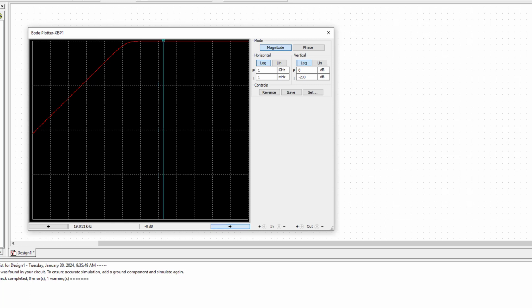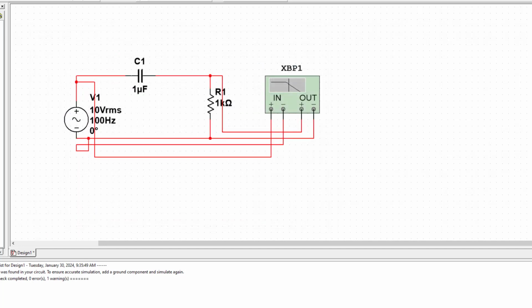the frequency increases, there is a 0 dB. 0 dB in the sense the complete input is just getting applied at the output. So the input is equal to output, and the effect of capacitive reactance is negligible. As the frequency reduces, the effect of capacitance comes into the picture, and the signal is getting attenuated. Attenuated in the sense that whatever input you are giving, you are not actually getting that at the output; you are getting less than that.